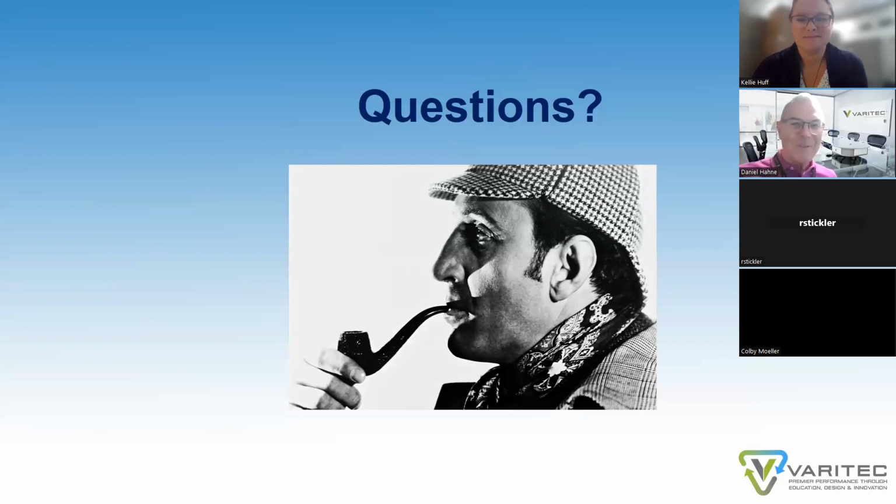So, we have a question. What effect do sound attenuators have? Sound attenuators will also provide system effect, because a sound attenuator is going to have baffles throughout the middle of them, and those baffles will impact the actual flow. Not to mention, a sound attenuator is going to have its own static pressure drop that is to be assessed.